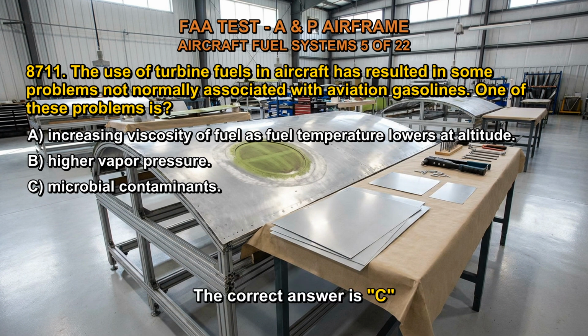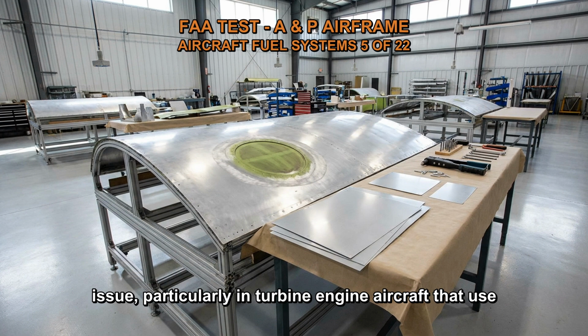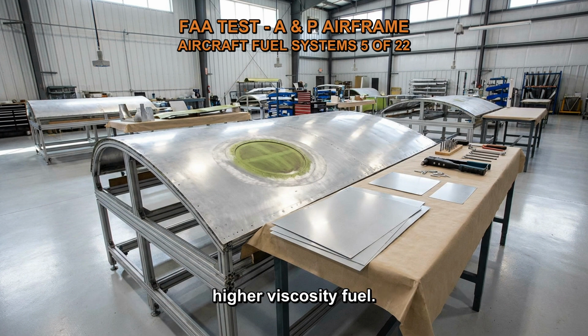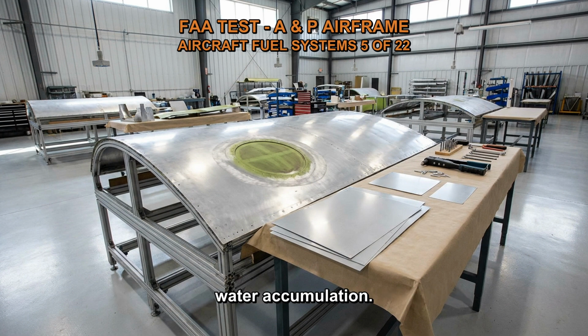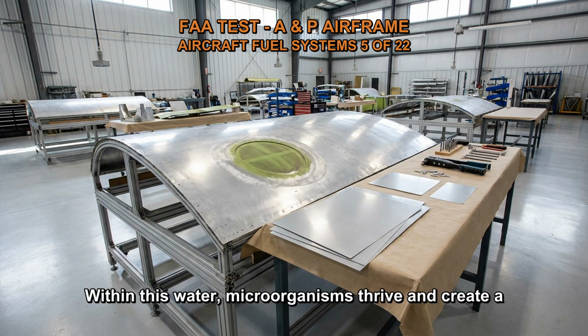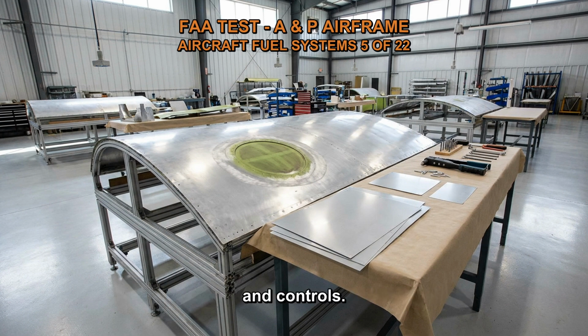The correct answer is C. Microbial contamination in fuel systems is a common issue, particularly in turbine engine aircraft that use higher viscosity fuel. Unlike gasoline, turbine engine fuel has a higher affinity for water, making it more susceptible to water accumulation. Within this water, microorganisms thrive and create a slimy layer that can obstruct fuel filters, lines, and controls.